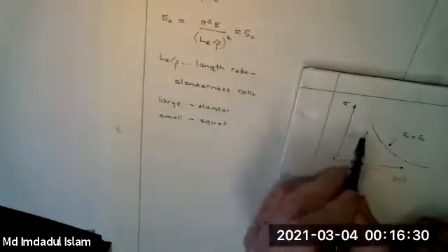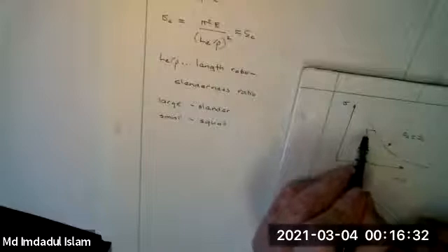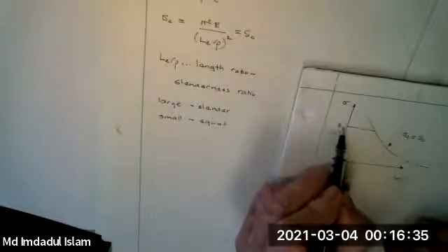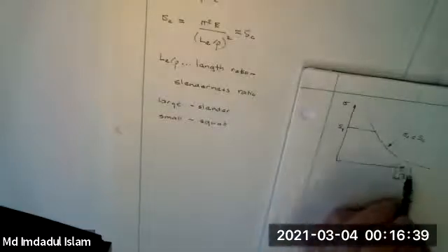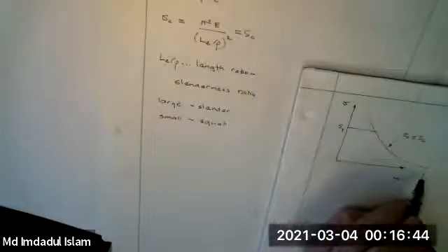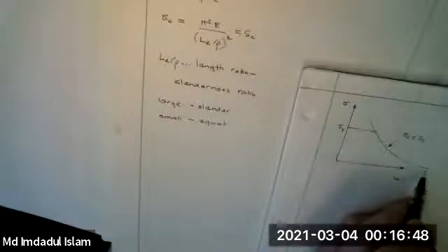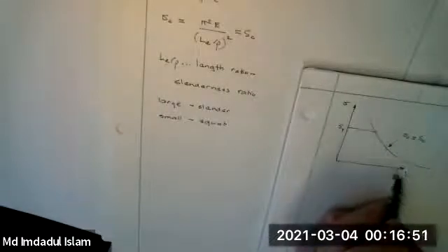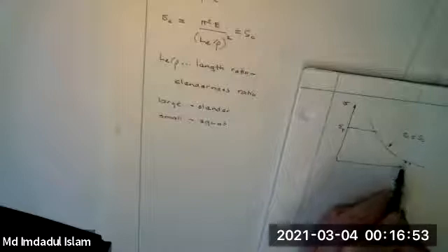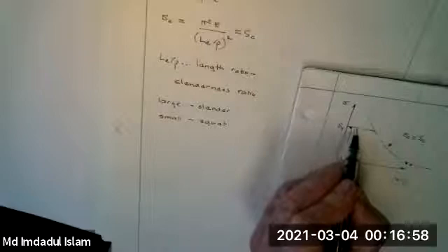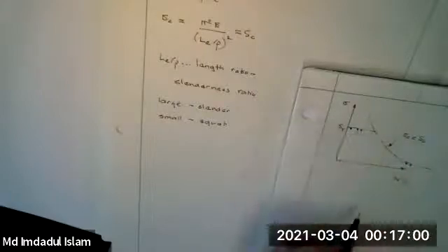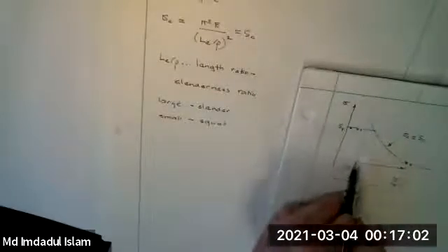As it gets shorter and shorter, there's also SY for yielding. So if you do experiments, if you get way out here and it gets very, very slender, it's a bit like the ruler, then things tend to buckle below this. But if you're not too short, then the data is pretty good. On the other hand, what you did in your materials lab, you probably got some points around here. There is a bit of a transition region.